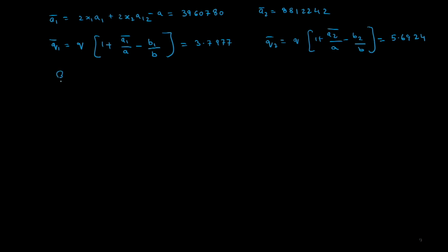The other thing I need in these calculations is beta, which is BP over RT. We already have B for the mixture from the previous slide. The value we had was 44.91. The pressure here is 30 bar. R is 83.14 times 373. This value works out to be